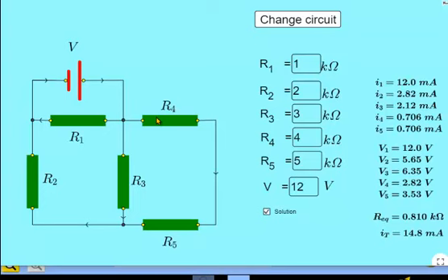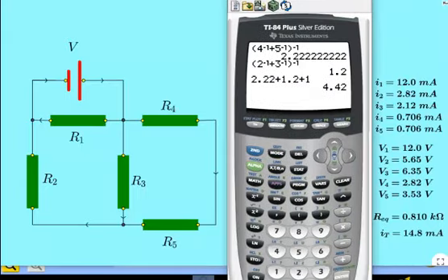All right, so this one actually is not too bad. Our 4 and our 5 are in series with each other, very obviously, and then they're in parallel with 3, and then all of this stuff here, and this is a little bit harder to see, is actually in series with 2, and then when I'm done with all of this here, that's in parallel with 1. And we're aiming for 0.810 ohms. So here we go. 4 plus 5, well, that's obviously 9.